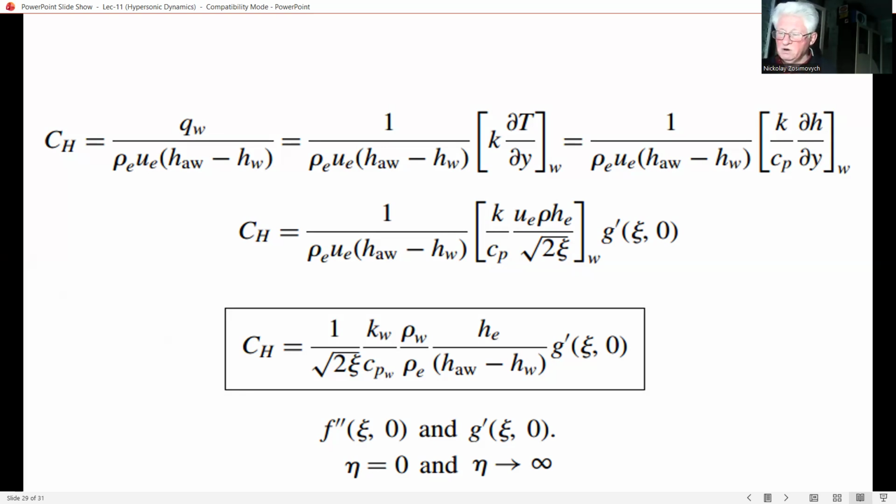In terms of the second derivative and first derivative at the wall, there is no way of obtaining them directly. Only a complete solution of the boundary layer will provide the results at the wall, the main practical results of any boundary layer analysis.